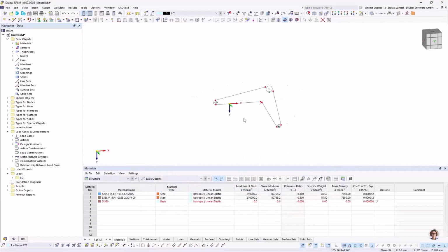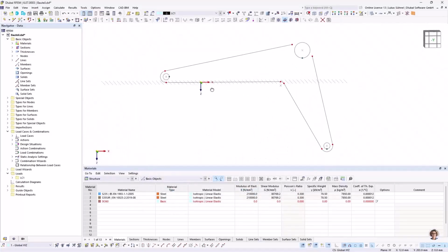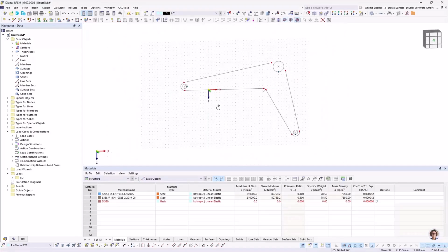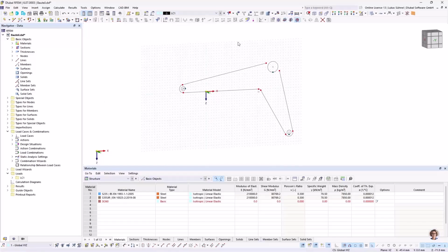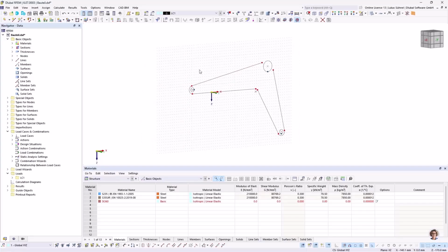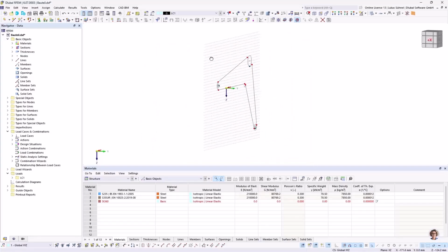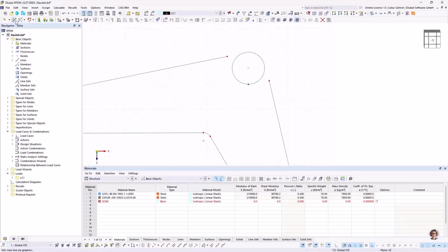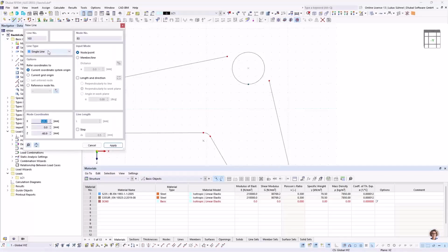So now let's zoom in. What I can see now is that it's still in the wrong plane, so I will switch it to a vertical plane. And now I feel much more comfortable modeling something because I know where my elements will end up. I also place this plane on my existing structure, not, I don't know, maybe 10 millimeters in minus y direction or something.